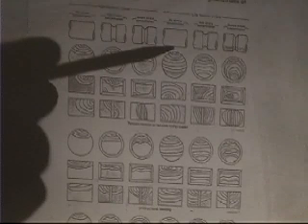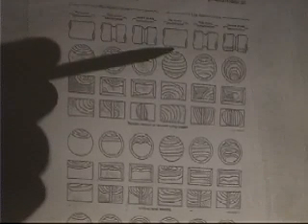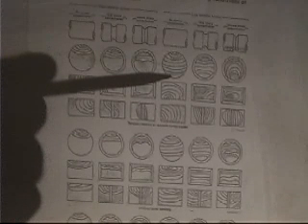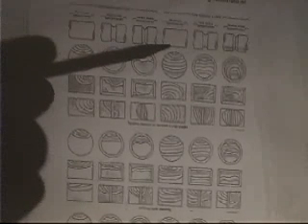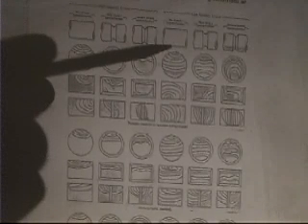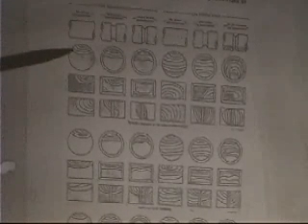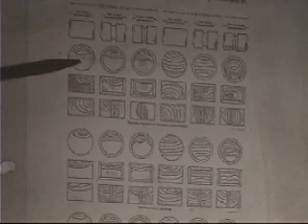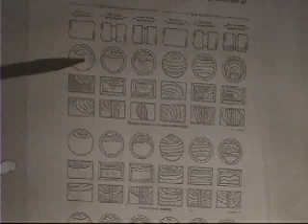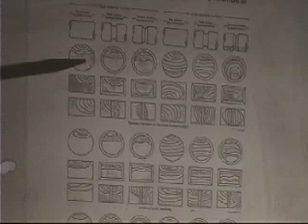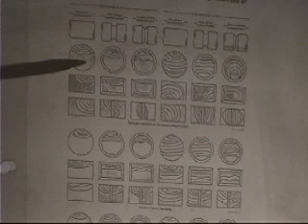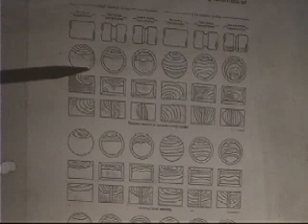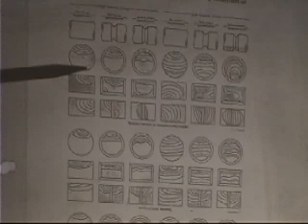That means there was some unusual event that caused it to initiate. Okay? It doesn't usually see high stresses, but the fatigue crack initiated, so it must have seen a high stress or an impact or something in its previous life. Whereas over here, it's at high enough stresses, you can expect that eventually it's going to fatigue. So this is the type of failure you see in most medical implants. You know, you have some spinal fusion or something, and they put some implant in your spine to hold things together. It turns out the metal bars and screws and things they put in your spine if you have a spinal fusion are not going to last as long as bone.